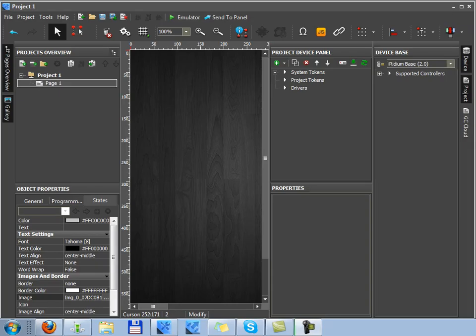As we decided in the previous lesson, Global Cache equipment is the best for controlling your system via IR channels. In this lesson, I will tell you how to set up control of equipment via IR with the help of ready Global Cache modules, iRidium GUI editor, and GC Cloud base of IR commands. When creating a new project, we have to set up its interface and fill in the project database.